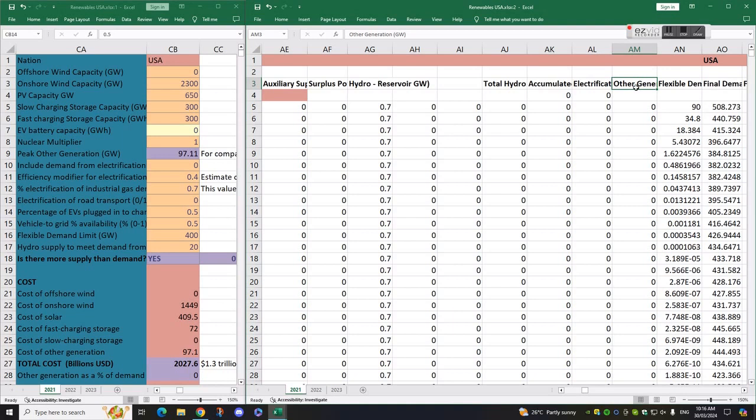So for a 100% renewable grid, this would have to be renewable sources which are readily dispatchable. So it could be biogas generators, basically what the open cycle gas turbines do currently. So peaker plants, maybe biomass, because often the other generation will be needed for extended periods throughout the night when there's low wind supply and the sun obviously isn't shining throughout the night. So demand might outstrip supply.